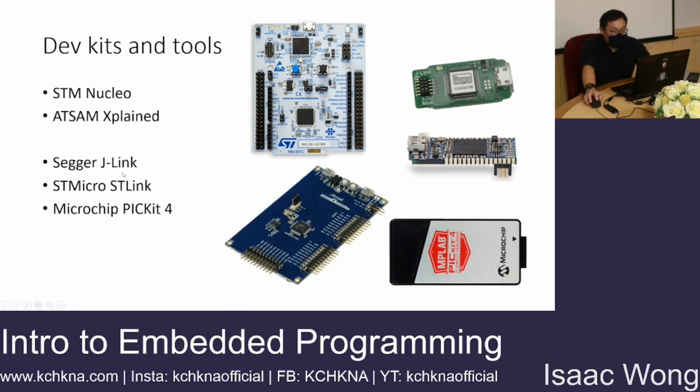Personally, I like to use the J-Link for my projects, because this is a universal programmer and it supports all kinds of devices. I'm using the J-Link Mini Edu. It's designed for educational use, and it's really cheap. But it has to be education. You can't use it for commercial applications. So for a research project, it's a really good tool because it can target all kinds of microcontrollers. It allows you to experiment with more things.